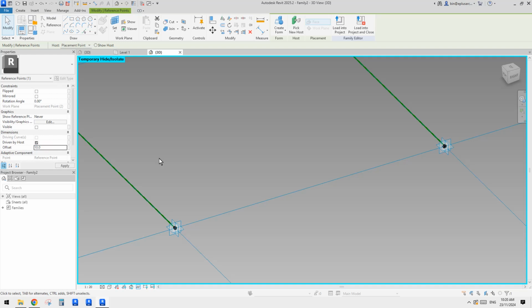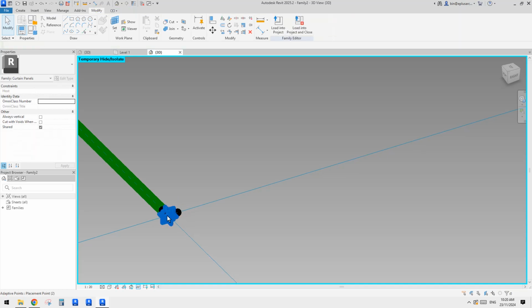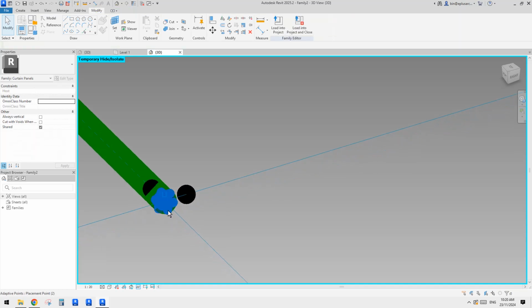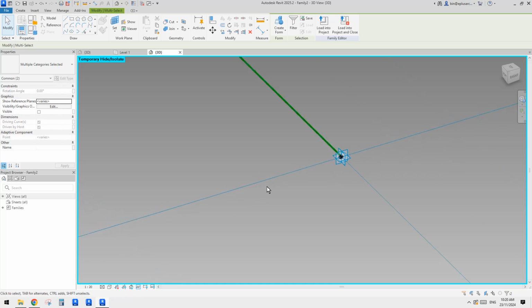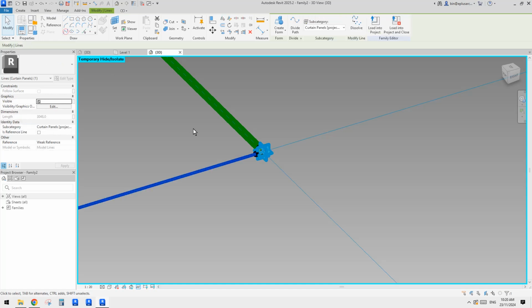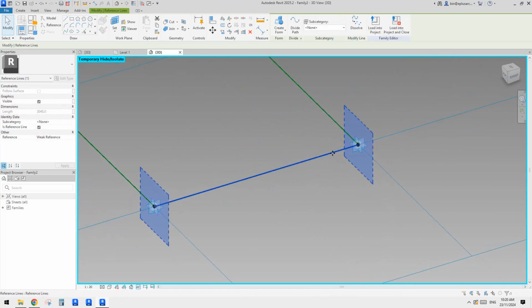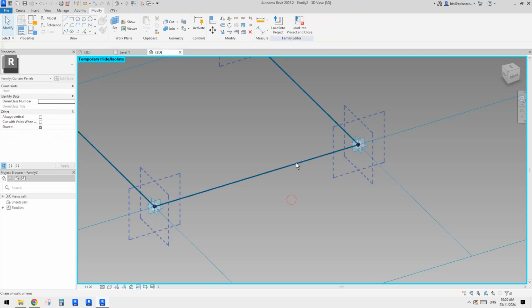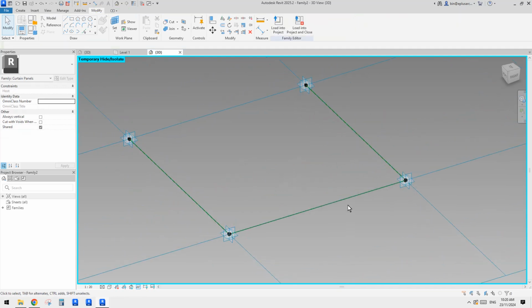Well, I'm not sure what that's called, but yeah. So this is a 10, okay, and then again, let's select the adaptive point, this one. So again, 1, 2, 3, 4, okay, 3 and then 4. I'm going to create a spline through points. So this time, this reference line will follow the divided surface direction, okay.